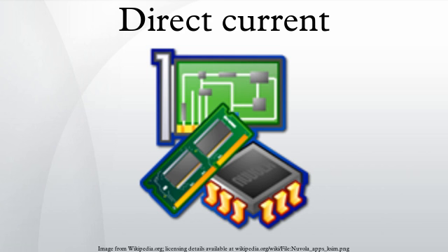Most electronic circuits require a DC power supply. Applications using fuel cells also produce only DC. The vast majority of automotive applications use 12-volt DC power. A few have a 6V or a 42V electrical system. Light aircraft electrical systems are typically 12V or 28V. Through the use of a DC-DC converter, high DC voltages such as 48V to 72V DC can be stepped down to 36V, 24V, 18V, 12V or 5V to supply different loads.